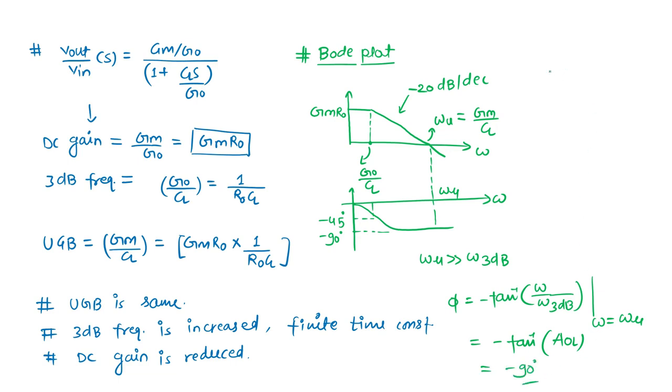So from here what we can see, phase margin is again 180 plus this angle, which is nothing but minus 90, so it is overall plus 90. So phase margin is still good, but ideally what we want is maximum possible DC gain, which is infinite. So ideal integrator tells this thing.